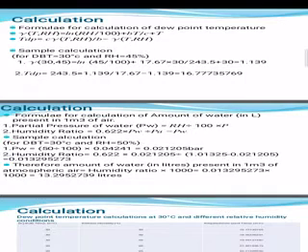As you can see, these are the two formulas which we have used to calculate the dew point temperature. First, I have shown you the sample calculation using the dry bulb temperature at 30 degrees Celsius and relative humidity at 45%. In the formulas there is a term B and a term C. These are the constant values in the dew point temperature. The B value is 17.61 and the C value is 243.50 degrees Celsius.